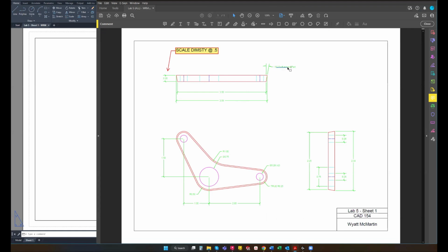What this draft tells me is that likely this is a molded part, either plastic or metal. Generally speaking, I have more experience with injection molded plastic parts. When you have an injection molded part, you need what's called draft, or it's basically a tapered edge. Usually 3 degrees would be the minimum amount of draft before you start getting pull lines on the part. And what it allows it to do is for the piece to slide nicely out of the mold. So that's what this draft is telling me, that this is some sort of molded part.